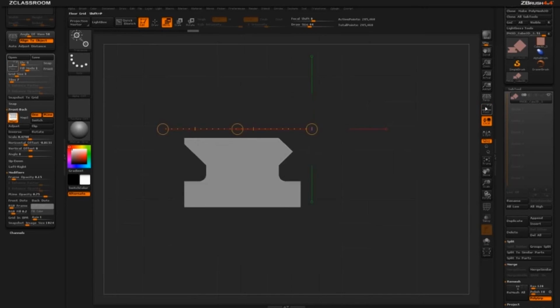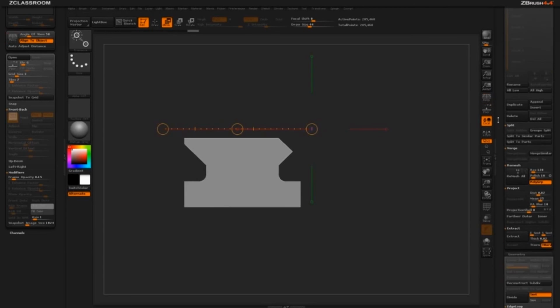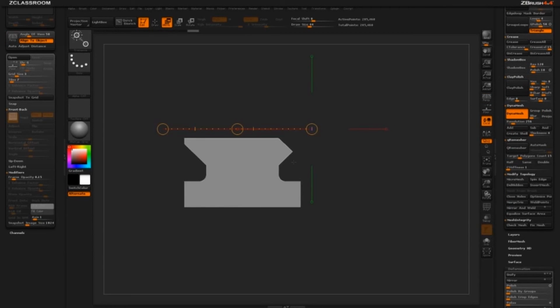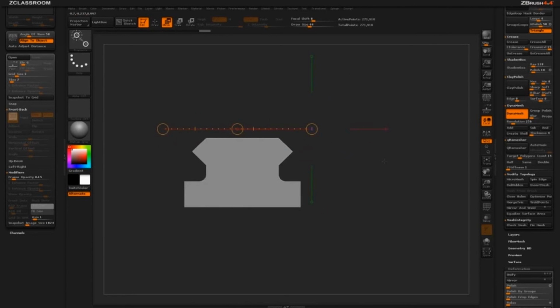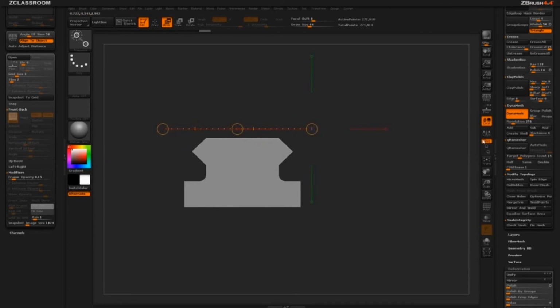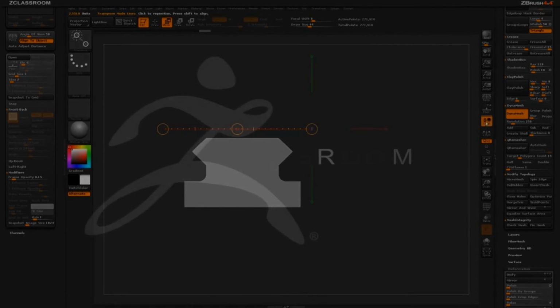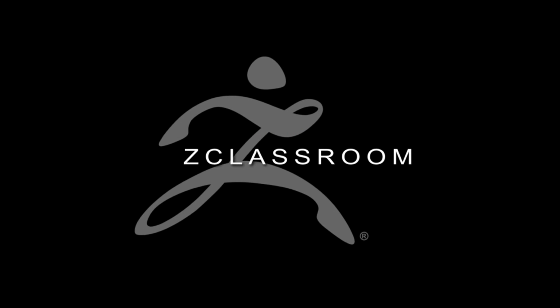You can see I have one side done, but the other side isn't done. Since this is a DynaMesh mesh, I can still use any of the other mirror and weld options, like we did for this subtractive piece here. So I can just come here and hit mirror and weld, and now I have both sides identical. It works really great for symmetrical objects, but if you don't have the luxury of having a symmetrical object, you could just mirror and weld the subtractive pieces and then position them where you need them to go.